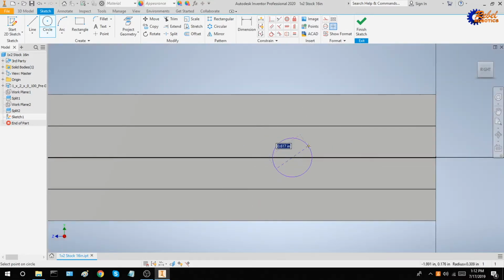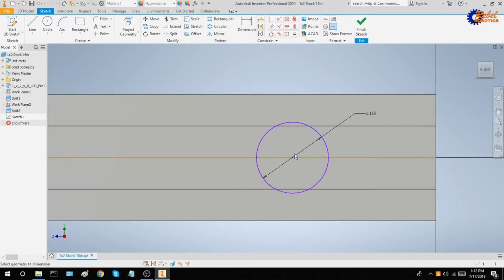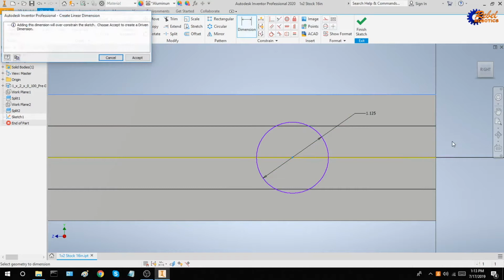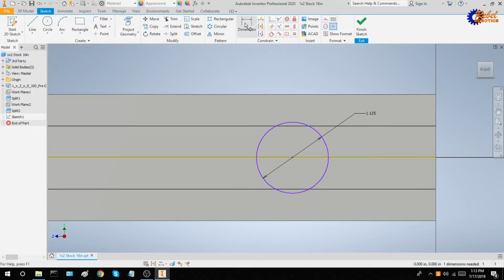We'll go ahead and make our bearing hole a diameter of 1.125, or 1 1/8 of an inch, because that's the diameter of the bearing. And we'll go ahead and make more specific dimensioning. We'll first check that this is 1 inch off, and that is so. And to offset it from the other edge, we'll do 2 inches for now.